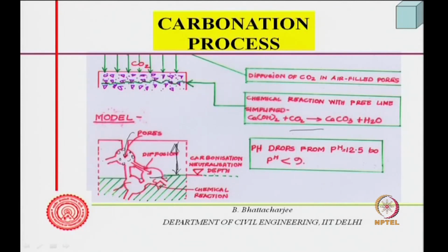is finished, we call it carbonation. The carbonation reaction has occurred, and it has carbonation neutralization. So, this is the neutralization depth, and that is the carbonation depth. So, we call it carbonation depth, up to which all the alkaline material has got neutralized by carbon dioxide coming from outside. So, again the pores are important, moisture situation is important.